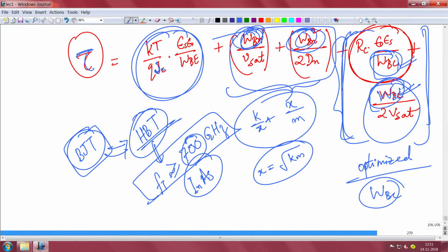So, what is remaining now is that we will visit BJT very briefly when we discuss compound semiconductor and heterojunction, because when you have compound semiconductor and heterojunction, then you can overcome some of the problems of BJT like emitter band gap shrinking and a low gain. Okay. So, that enables you to get high gain despite emitter doping being very high. So, those things we will just touch base when we talk about heterojunctions and compound semiconductors.